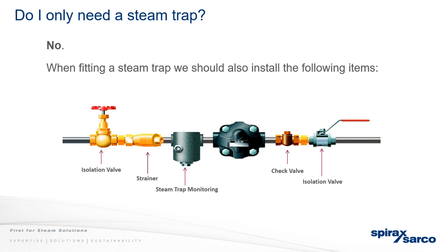The thermodynamic is a more cost-effective way of going for it. And if there's no pump and you want to send it directly back to the boiler house, that is fine, provided there is enough differential pressure across the steam trap. Yeah, so you can do that by manufacturing drops and whatever else, so you can get head pressure.